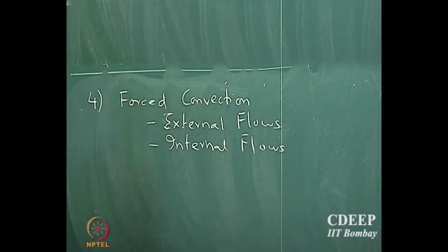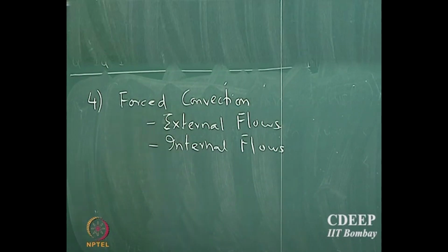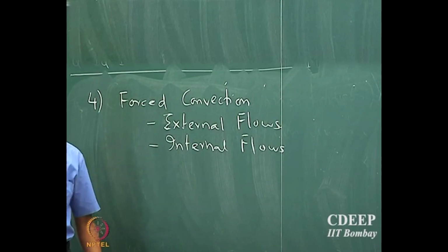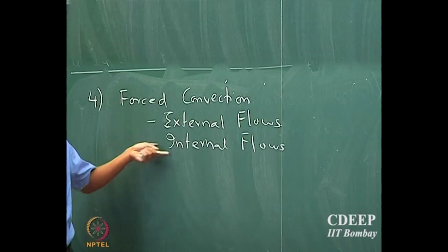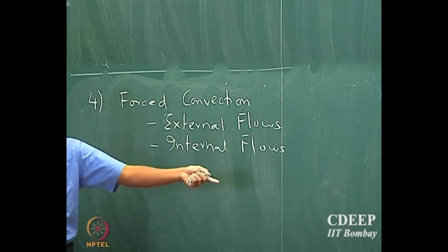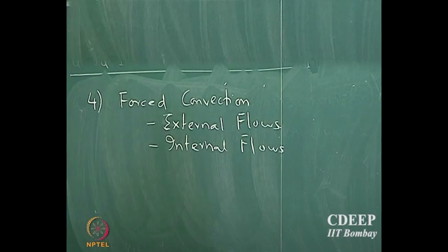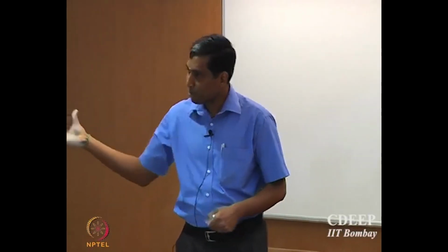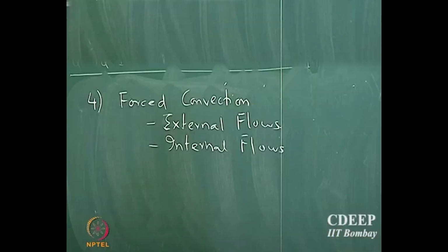Okay. So, let us take a look at the pipe example I described a short while ago, where you have a fluid which is going through a pipe, and there is another fluid which is flowing past the pipe in the exterior of the pipe. Now the heat transport from the fluid to the wall inside the tube would be governed by what is happening inside, and so that will be covered in the internal flow section. And whatever is happening outside, because it is flowing past a curved surface area, the exterior of the tube, that is what is called an external flow.